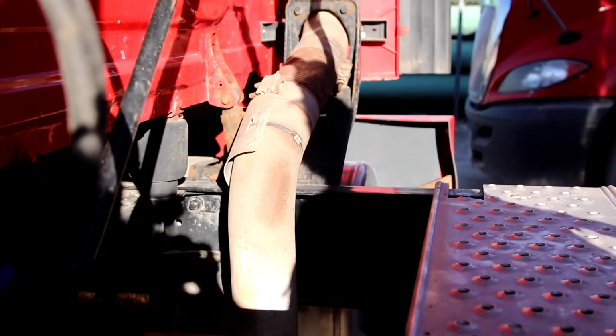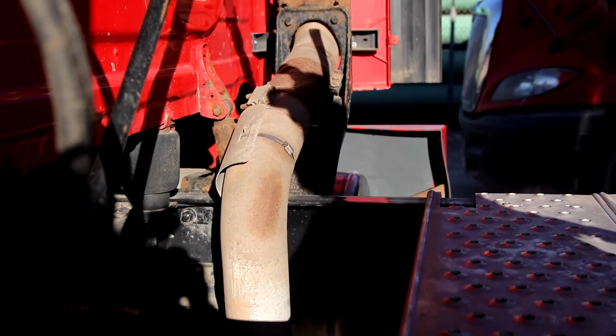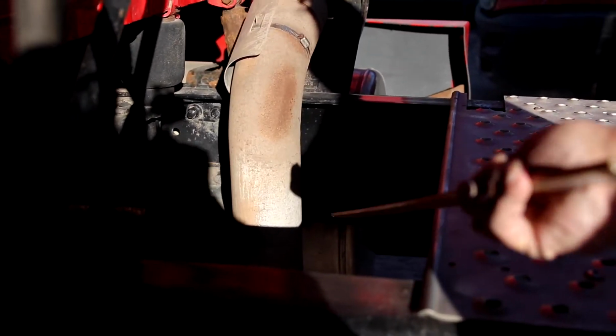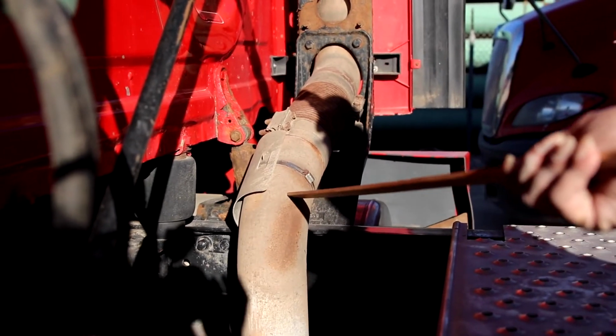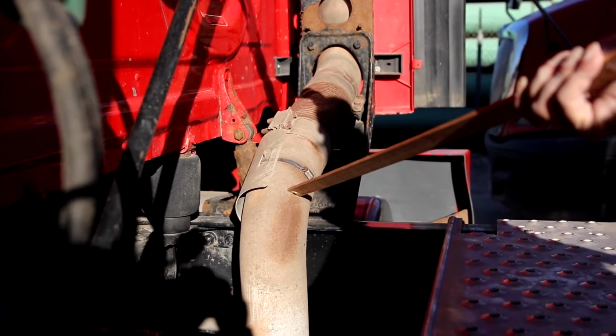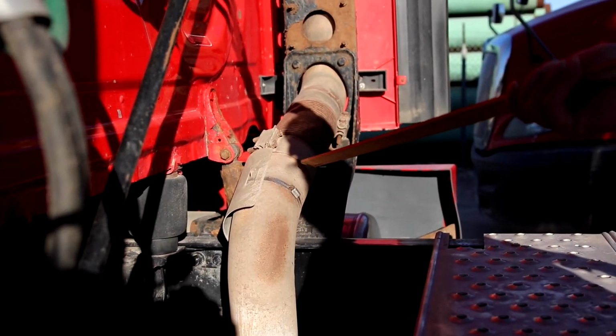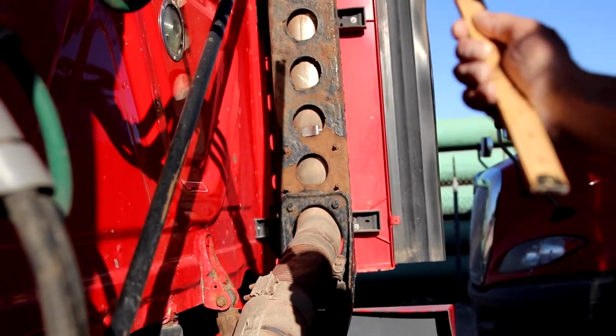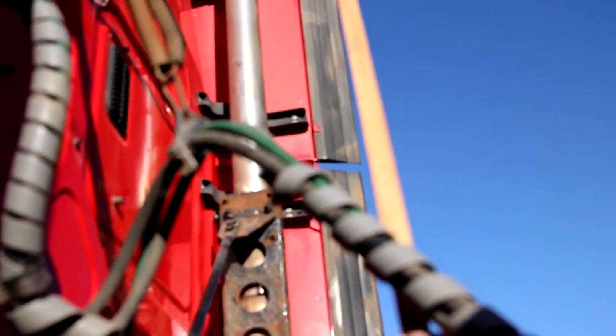This is your exhaust system. Some trucks have a stack running up. Some will have one that breathes on the ground. This one has a stack running up. What you're checking for is any signs of damage or black soot. Usually comes out of flex pipes. The only soot that should be coming out is up here at the top of the exhaust stack.